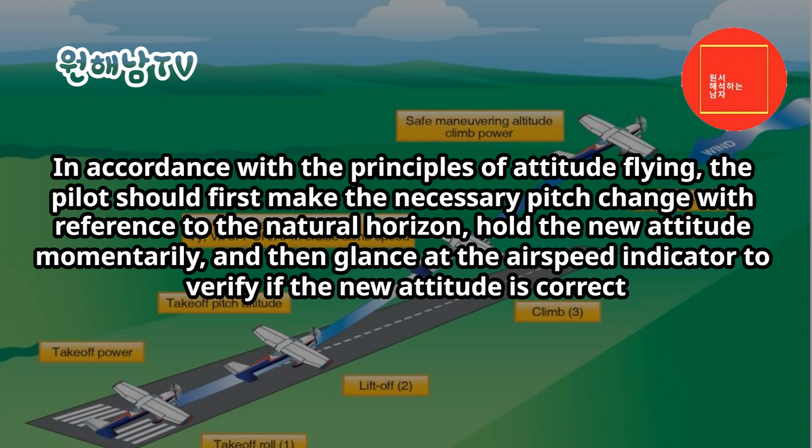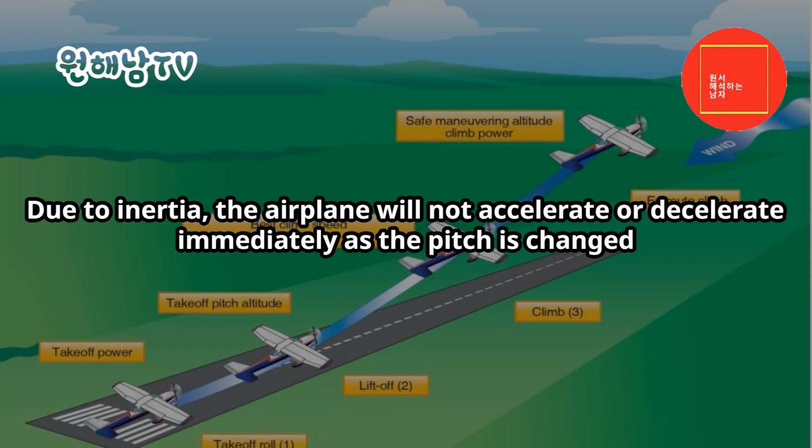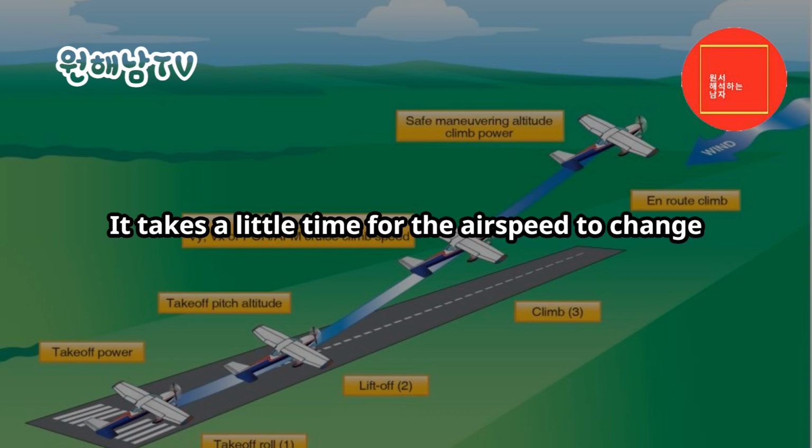In accordance with the principles of attitude flying, the pilot should first make the necessary pitch change with reference to the natural horizon, hold the new attitude momentarily, and then glance at the airspeed indicator to verify if the new attitude is correct. Due to inertia, the airplane will not accelerate or decelerate immediately as the pitch is changed. It takes a little time for the airspeed to change.